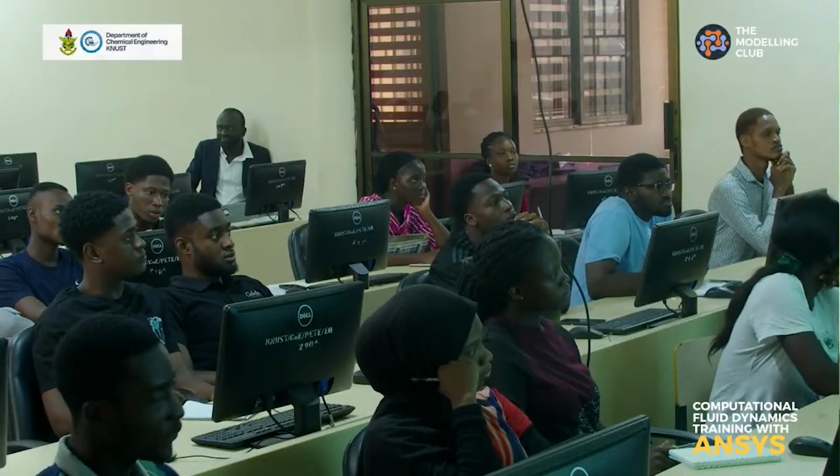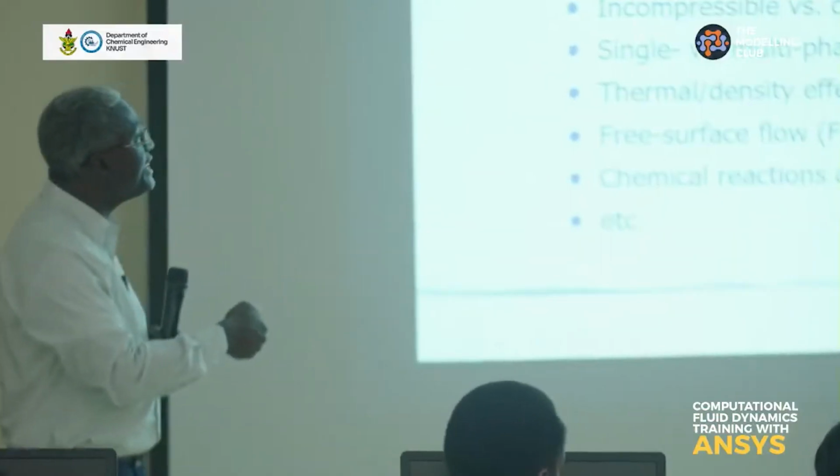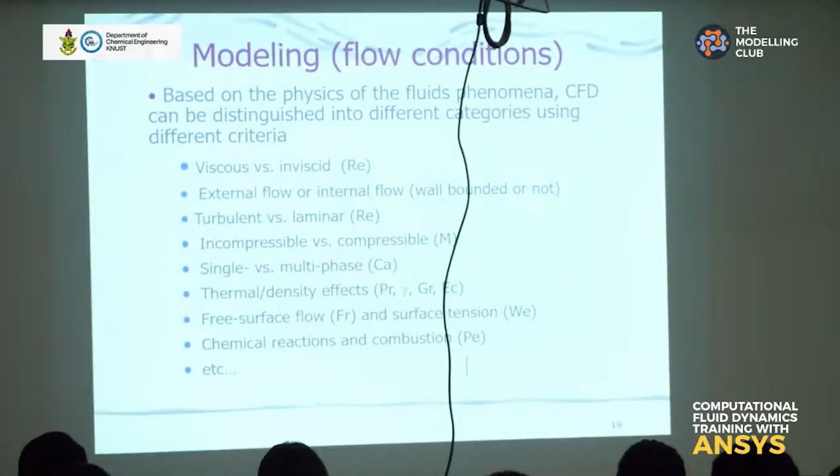2,100, 2,300. Very good. So this is all we are saying here: a quick back-of-the-hand calculation in doing your analysis, and you establish that we don't have to worry about turbulence. We are just dealing with laminar streamline flow in the system. So we have to decide that.